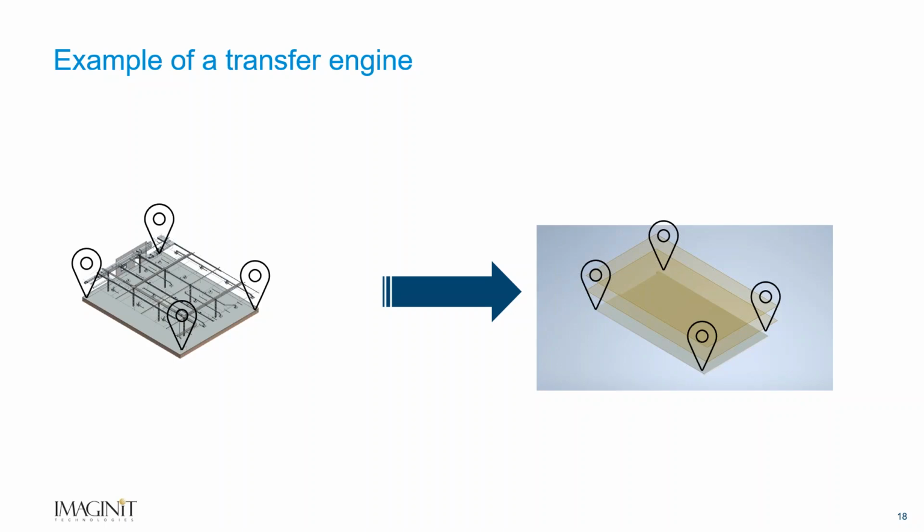I think you did a great job talking about that, and really open up your minds, everybody, on what this could be for the linking capabilities. You could be doing exterior cladding systems, and you're engineering and designing in Inventor each individual panel, the structure behind it, the clipping system behind it. But we need to bring that information into Revit and identify in cladding elevations which panel types are where on what facade. We can automatically bring that data in as rich Revit content, as each individual piece that can automatically be tagged. So there are many different ways to look at it, not just cladding. It could be interior components also.